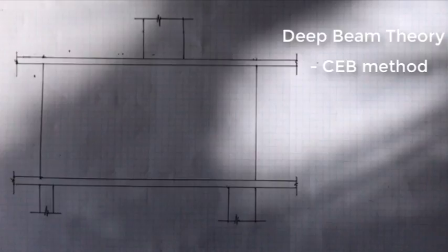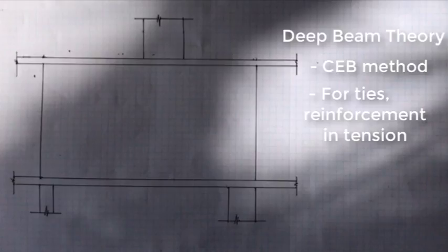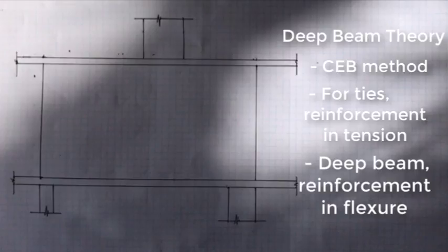So the main difference between the strut and tie method and the deep beam method is the tensile reinforcement. For the strut and tie method, the reinforcement is pulling, so that's in tension. For the deep beam method, it is actually in flexure, just like a normal beam. If it's in flexure, the development past the very ends of the column is not as critical as it is for the strut and tie method, because the maximum bending moment will be at the centroid, so the maximum tensile reinforcement required is at the center of the span.